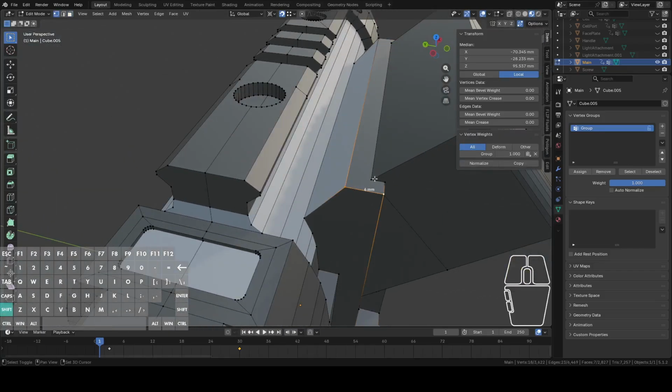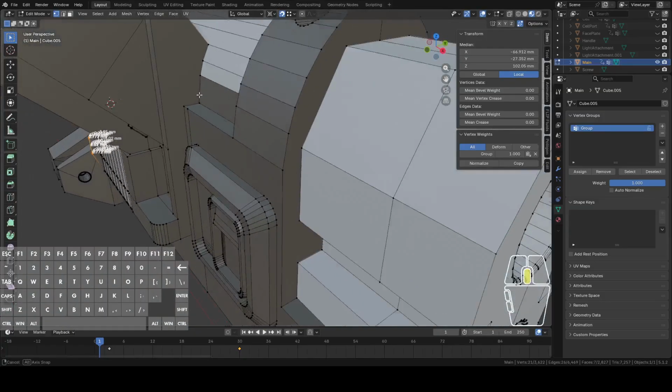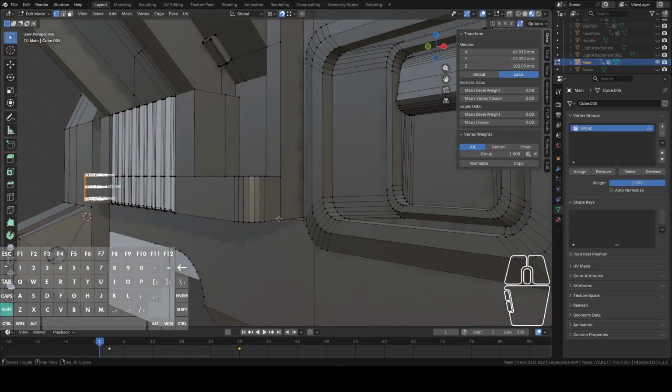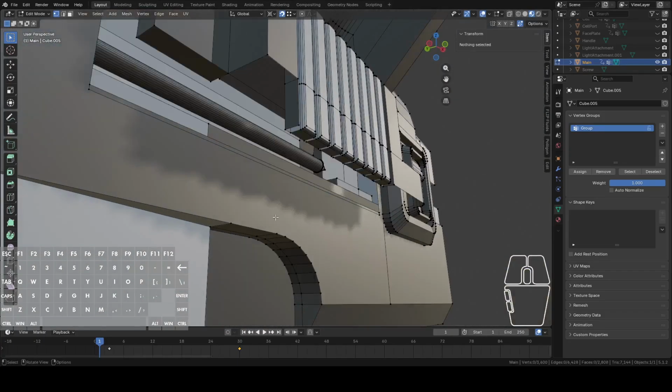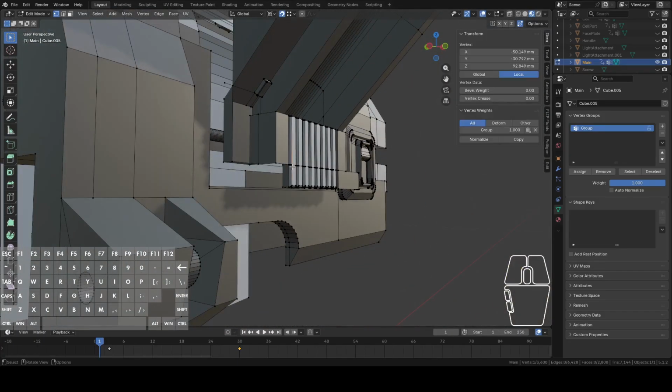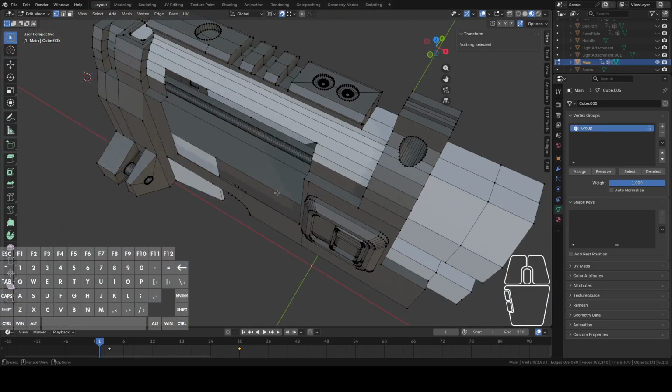And then knife project a square onto the side of this. I think that will be a much more efficient manner by which to get this done. Let's get rid of these, and then that should dislodge this, so I can hit L and select all of it, right clicking.